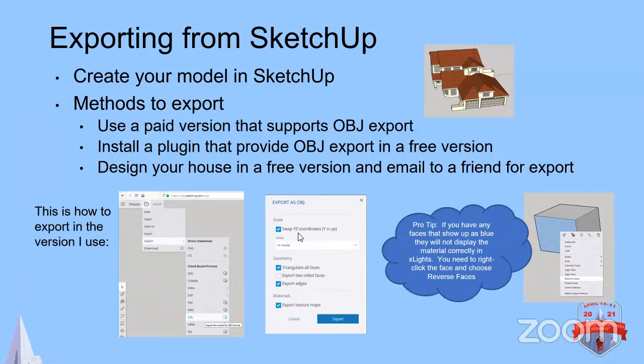So you need to swap your Y and Z coordinates. Whatever program you're using, if your house looks like it's flipped up sideways, you probably need to swap your Y and Z coordinates because a lot of programs use Z as up and xLights is using Y as up. The other thing, you want to triangulate all the faces, and export the edges if you want to be able to see the black lines on the edges of your house.